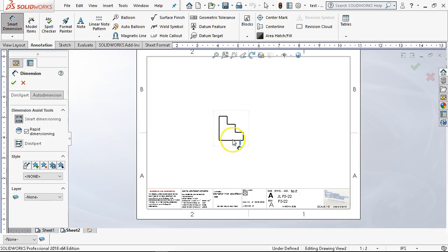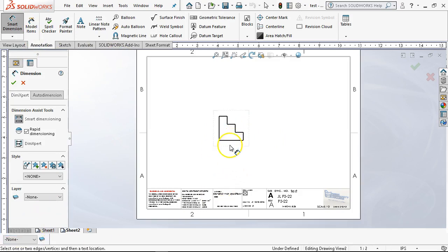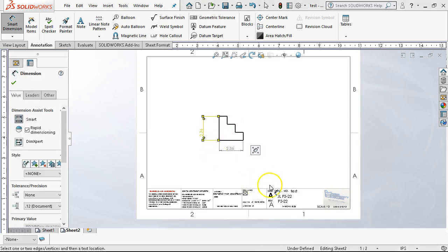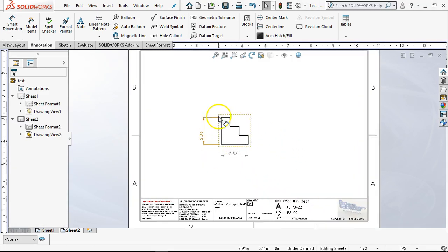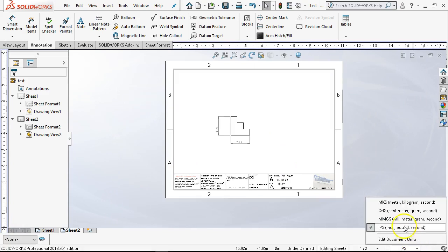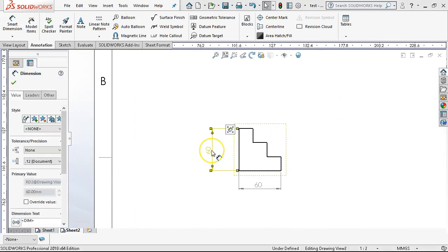So I go into the smart dimensions. Let's see, does this have? No, it doesn't have my layer set up for dims and center. So 2.36 by 2.36 tells me that's 40 millimeters by 40 millimeters. I recognize that number, but it does not give me the desired result. Oh, 60 millimeters. How did that happen? Can't do math, apparently. That's right. 6 millimeters is 0.236.